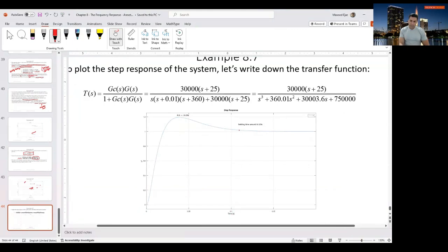So whatever is the settling time condition, remember settling time condition was supposed to be like 4-time constant or 5-time constant. So I did not calculate the time constant of the circuit. You can easily calculate the time constant of the circuit when you take the roots of the denominator. And you can see which value of the root is closer to the 0 axis. That is going to take longer to settle down, and that will be your dominant root.